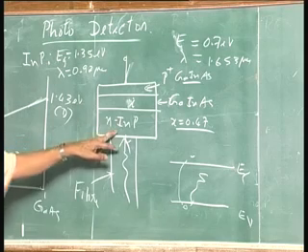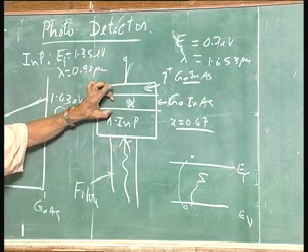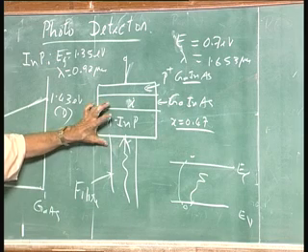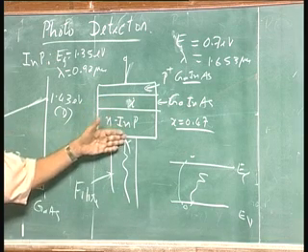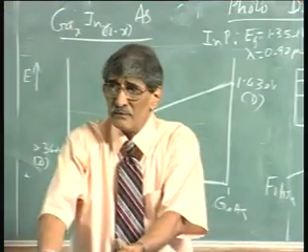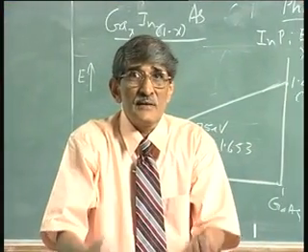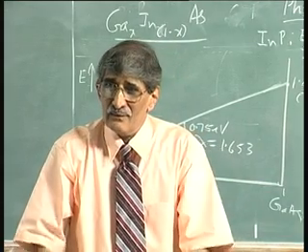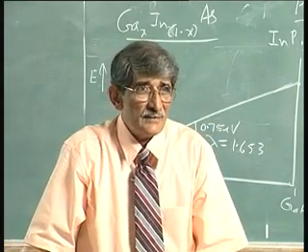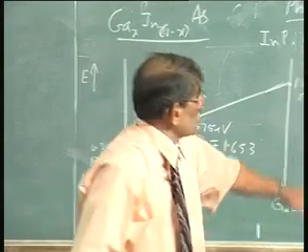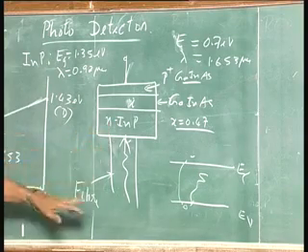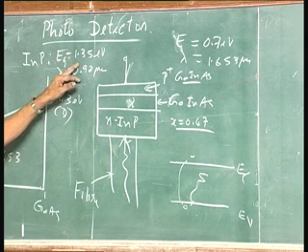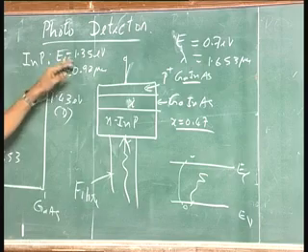It will be absorbed by that. And this is a thick layer, this is very thin, 0.2 microns or 1 micron. So, if this is 100 microns or 200 microns, whatever light is falling here is absorbed here. It is just absorbed in the bulk. Hole electron pairs are there in the bulk. What happens if you generate hole electron pairs? They just recombine, fall back, no effect. Okay, that is all. It is converted into heat, then it recombines. So, there is nothing happening there.